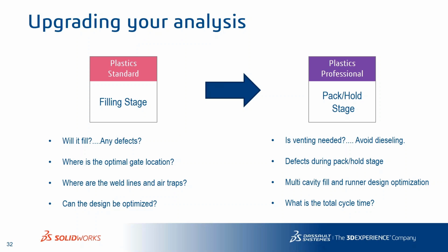So something that we've never been able to do in the physical stage, but now we can try to figure out that, hey, maybe we are holding the molds, that holding pressure is too much, and that's what's causing the problem. So maybe we need to release that a little bit more. Plastic Professional also gives you the ability to do a multi-cavity fill, and obviously that runner design optimization. If you are running a different, like a left and right part in this case.